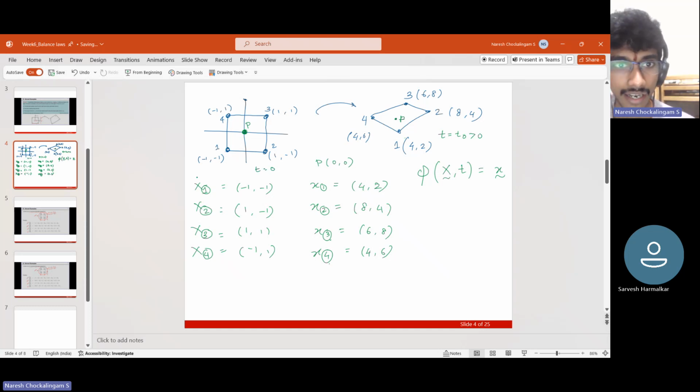So initially we are referencing 4 nodes, and the 4 nodes are at these points. So we are taking just a unit by unit square, and you're putting the edges of these 4 unit squares. And after deformation, you're looking at the same 4 nodes, where they are going. They are going to these points. Therefore, this basically defines a discrete deformation mapping.